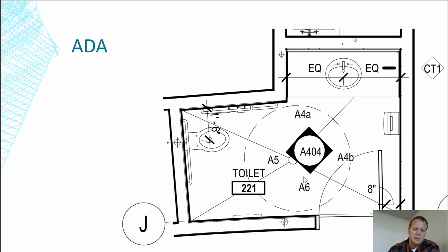That's a 5-foot turnaround for this area. And look at that, 1 foot 6 inches. Guaranteed that dimension is right there because of ADA compliance. And so the point is, as you look through different rough plumbing, definitely on the job site, pay attention to your ADA rooms. Know where they are. Know exactly what the dimensions have got to be.